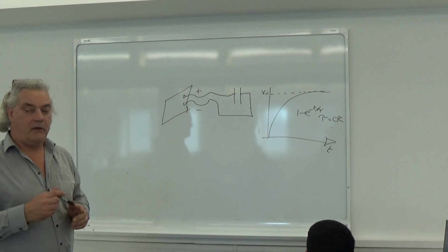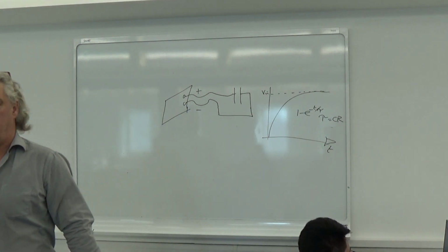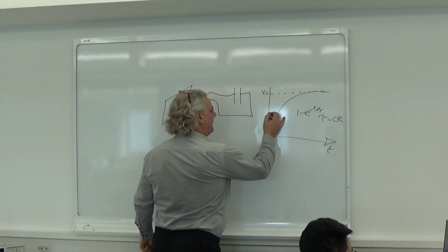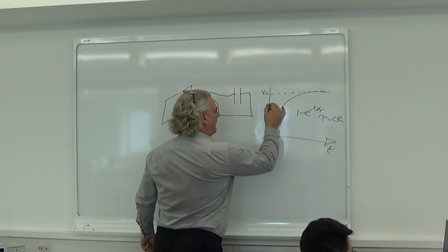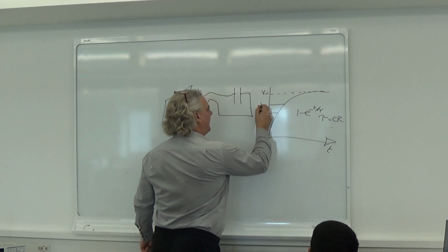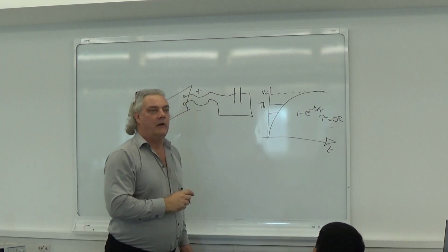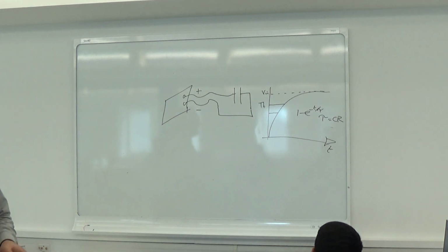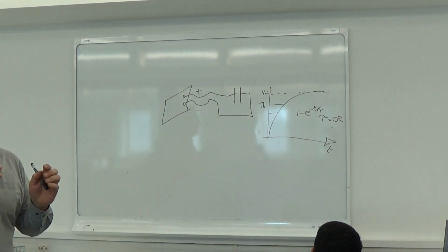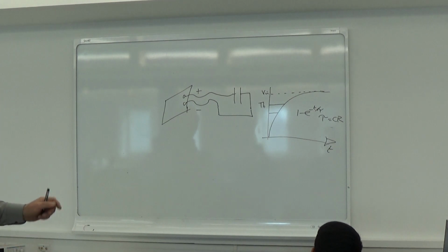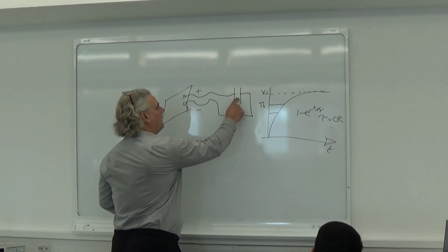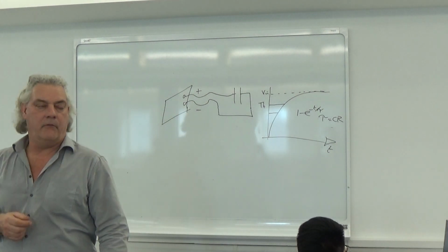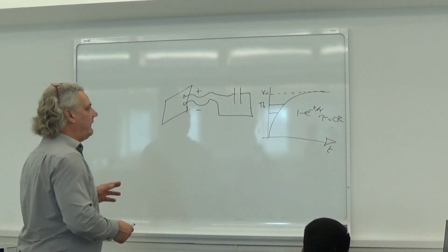So you're all comfortable with that, and you're building circuits which are firing according to the voltage threshold. So the cases we saw last week is, we might say this is TH for our threshold. At that threshold, we want this circuit to dump, not everything, because it won't go right down to 0, but we want to dump as much as we can out of the capacitor and into a load, which is the robot doing some work. It moves, that's what we want it to do, right? So that's what the circuit is all about.